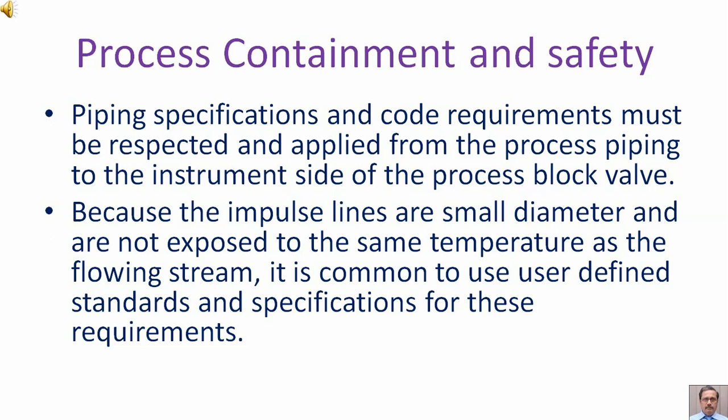Because the impulse lines are small diameter and are not exposed to the same temperature as the flowing stream, it is common to use user-defined standards and specifications for these requirements.